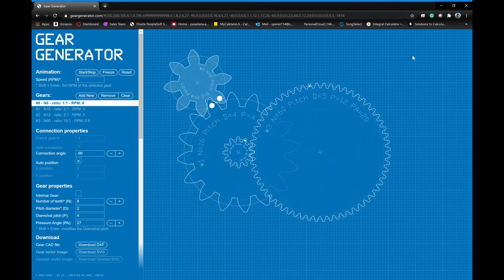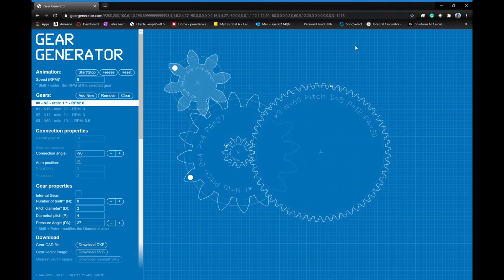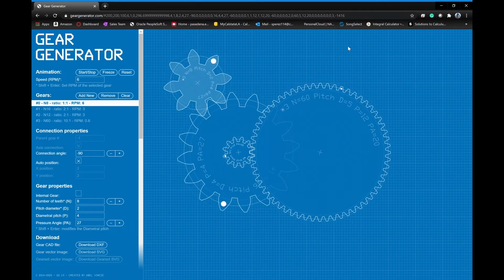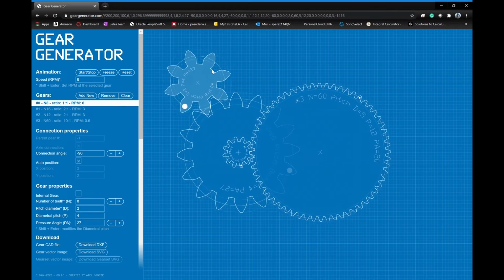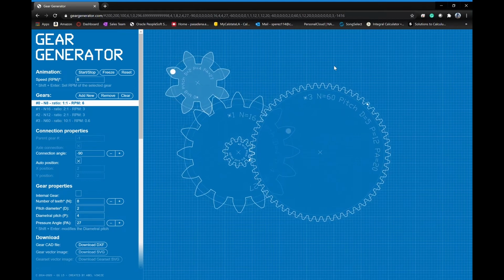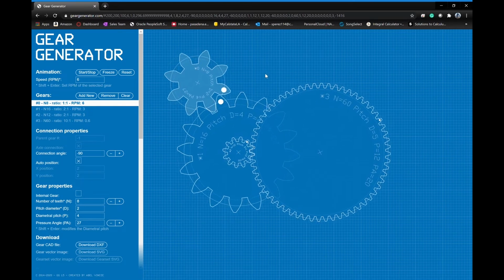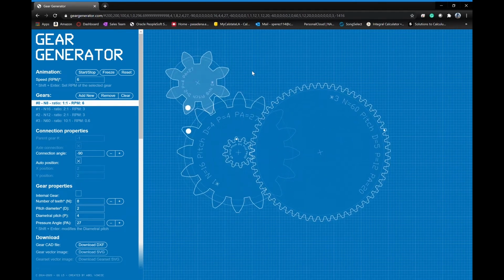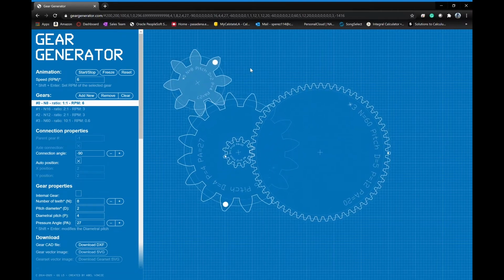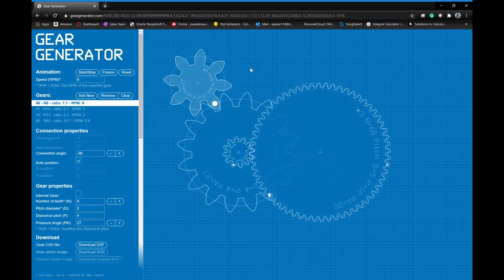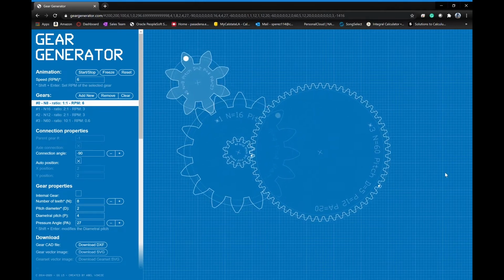There are a few limitations as to what we can do. If you're working on your gearbox for your team, then you're going to know what your input shaft is going to be. Depending on how large your input shaft is, you're going to know what distance you can go from the edge of your input shaft to the valley between your teeth. I don't know what that might be for your team. We have a specific distance that we are comfortable going to. You have to do some analysis to determine that you have enough wall thickness between the edge of your input shaft and the edge of your teeth. So just make sure that you check what that configuration is going to be.